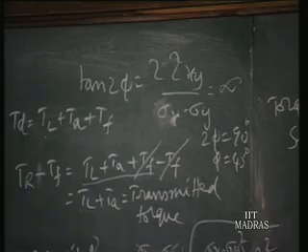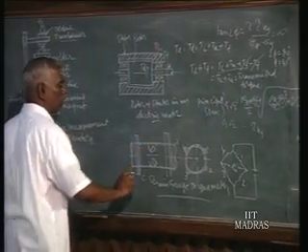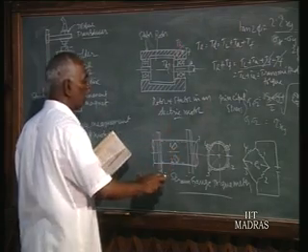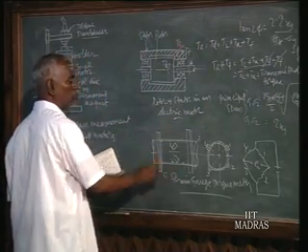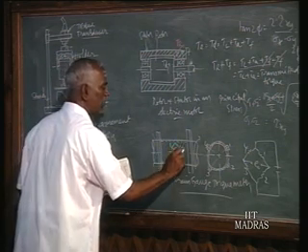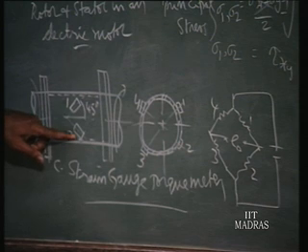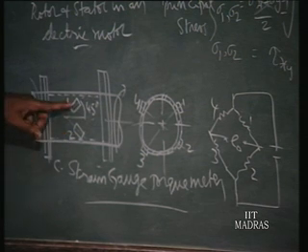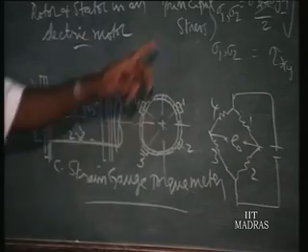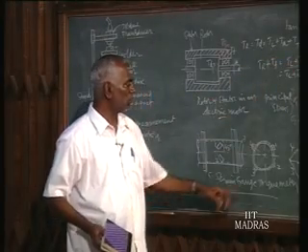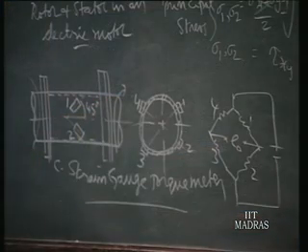So, this is the torque; we wrote this in the opposite direction. The shaft is twisted this way, that is, the torque is the shear stress in this direction. So, 45 degrees to that is how you have to fix the strain gauges. If one is taking up the tensile strain, then 2 will be taking up the compressive strain. Similarly, at the opposite point, at 45 degrees you have to fix them. So, 1 and 3 will take tensile strain, and 2 and 4 will take compressive strain.